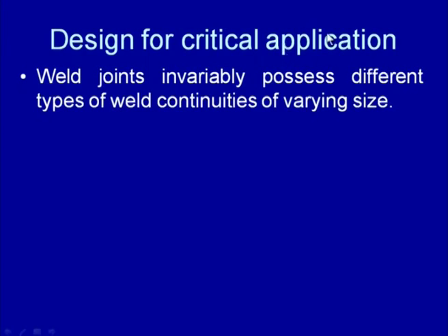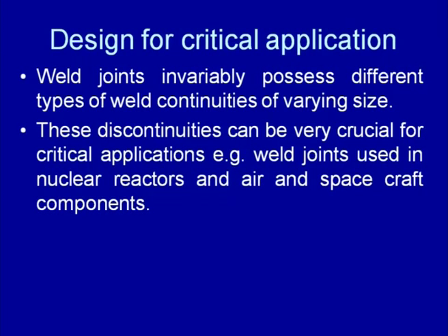Therefore, for critical applications the design of the weld joint should consider the presence of the various discontinuities present in the weld joint in different sizes, and these discontinuities can be very crucial for critical applications, especially nuclear reactors and aerospace and aircraft components.